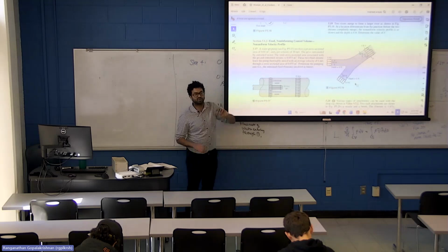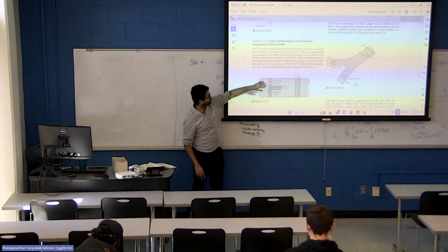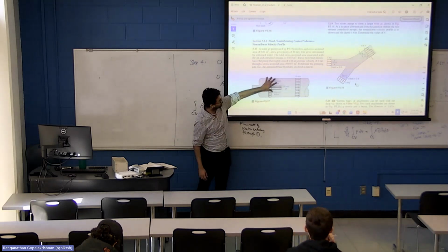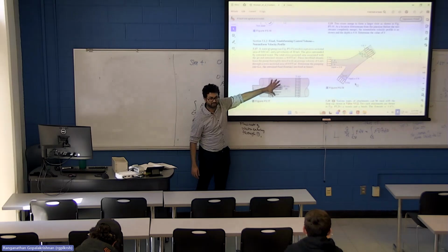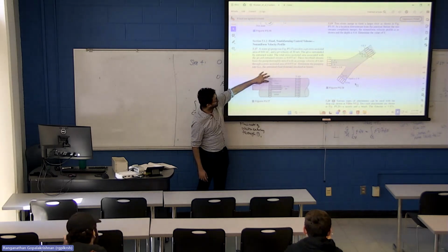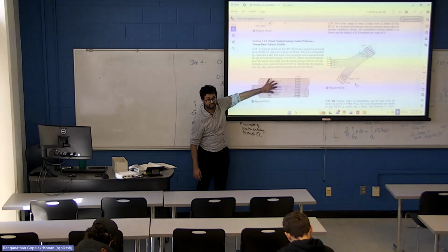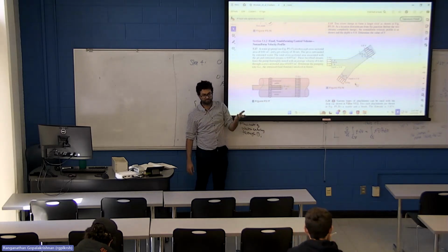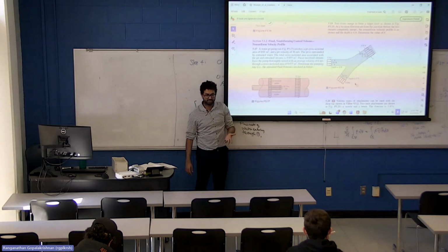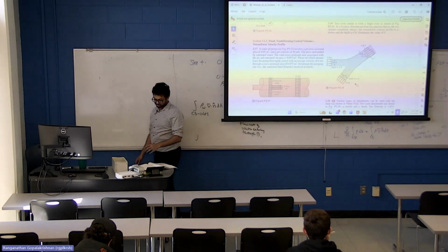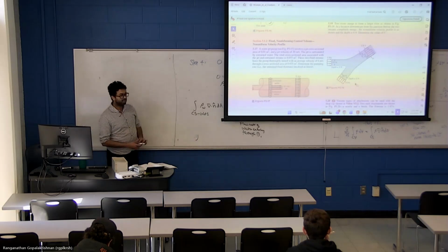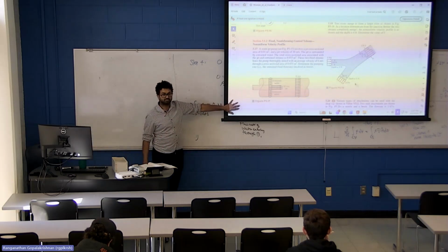Okay. So two things. First is the control volume coincides with the pipe, is of the same cylindrical shape. Number two, at every control surface, the velocity is uniform. So we just have to take the velocity and multiply by the cross section to get the flow rate. We don't have to do any integration. Okay, so let's do this calculation. Can I take this down? Yeah.